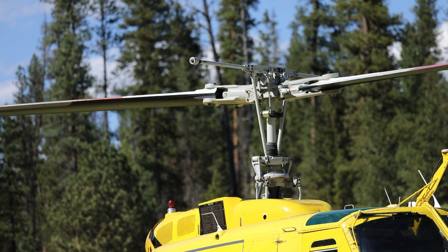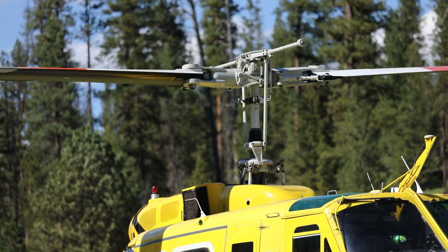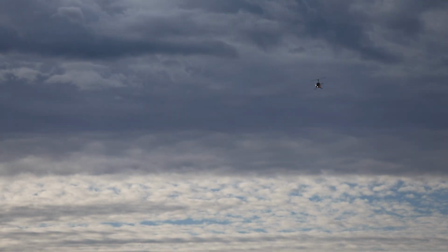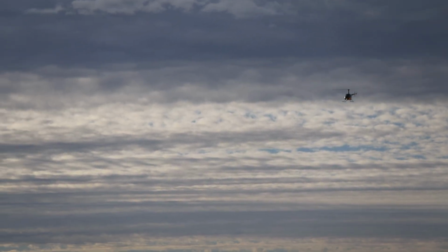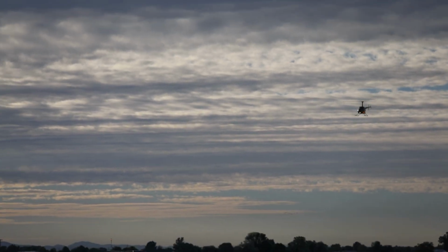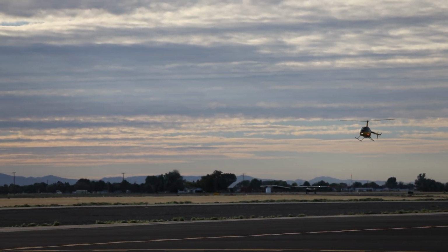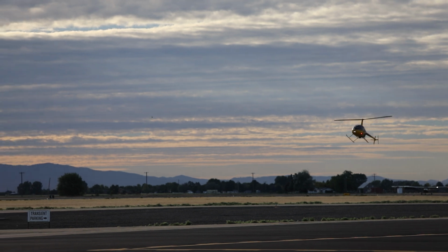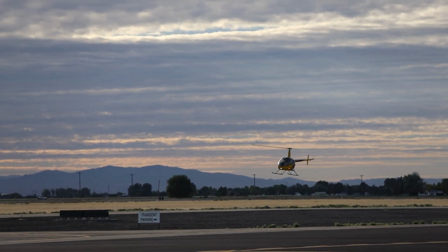During powered flight, air flows through the rotor system from the top and out the bottom. Helicopters have a freewheeling unit which automatically allows the main rotor to rotate freely if the engine fails or there is some mechanical emergency. The rotor system then maintains flight RPM by reversed airflow. The pilot has full control of the helicopter during the maneuver.